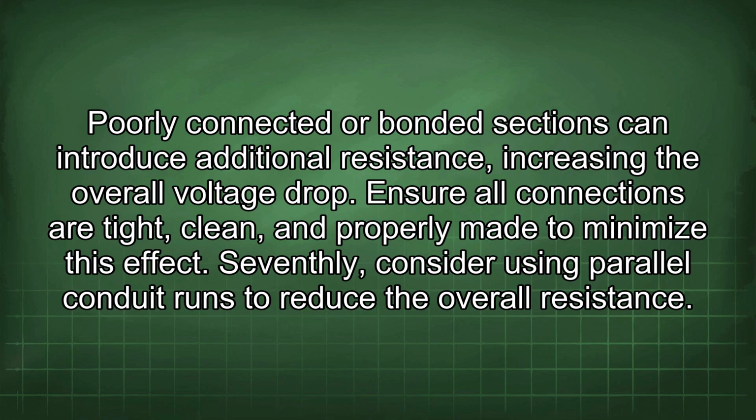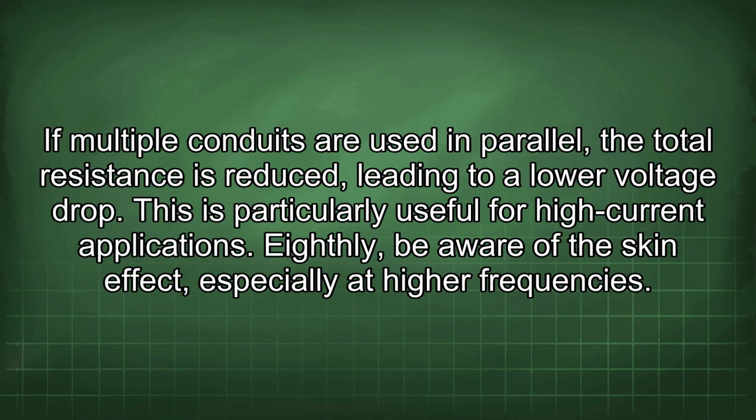Seventhly, consider using parallel conduit runs to reduce the overall resistance. If multiple conduits are used in parallel, the total resistance is reduced, leading to a lower voltage drop. This is particularly useful for high current applications.